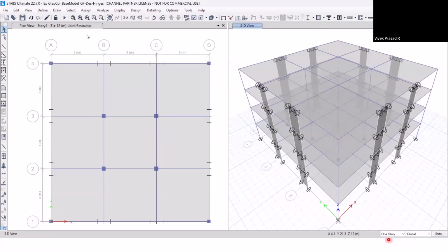Hinges basically define the post-yield behavior, or the moment curvature or moment rotation relationship that will be used to describe the post-yield behavior, whether it is a beam, which is subjected to bending moments that can yield, or for columns, it will be interactive axial and biaxial moments, P, M2, M3, or for walls, P and M3 interaction, right?